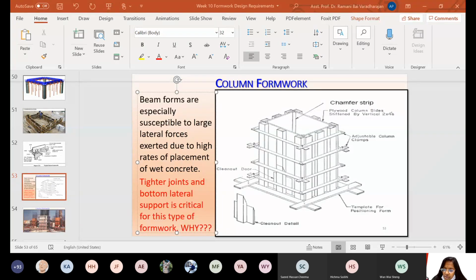If it is precast also, again the joints problem. Either it may be a precast one or the formwork. When you talk about the formwork, it should be in situ. When you start pouring concrete, you cannot pour at one stage, right? You start pouring here, and then parcel by parcel you will be doing it. The concreting cannot be done at one stretch, isn't it? Concreting is done for the whole length of the beam, part by part.